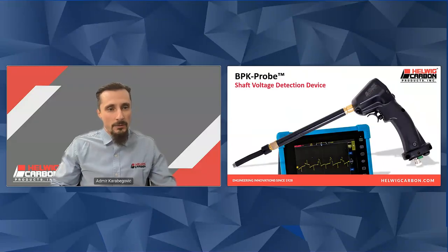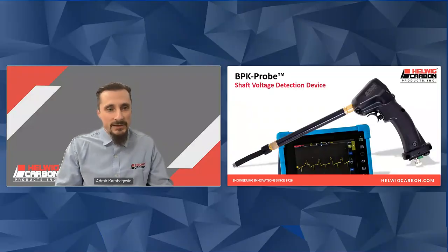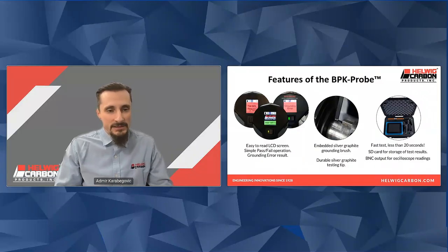So this is our bearing protection kit probe. It's an easy technician's level device to check for shaft voltages. And here are the features of the BPK probe. It has a very easy to read LCD screen. It has a simple pass-fail operation and can also detect ground errors, which is helpful in cases when you're troubleshooting these types of applications. We know ground is extremely important in motor applications.